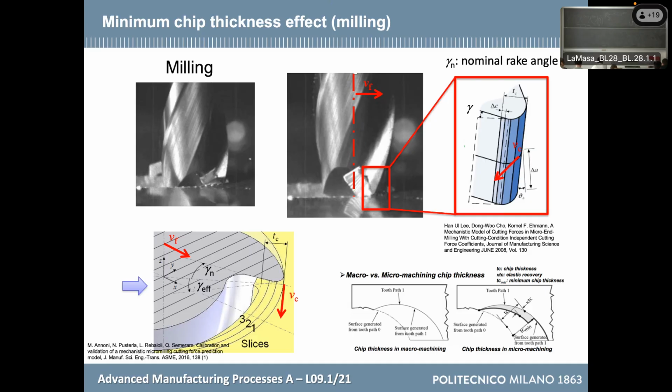Okay? I said that you never see a mirror-like surface. In reality, if you select a really small Fz and you have really good tools that are really sharp, for example, diamond tools with a radius of about 1 micron, on aluminum, you can have surfaces that are like a mirror. So the striations exist. So the milling operation is good. Every cutter has left its striation, but the order of magnitude is so small that our eye and also an instrument measures a roughness that is some nanometers by milling, but you need to select the right tool. In any case, this phenomenon is always happening in macro milling and micro milling.